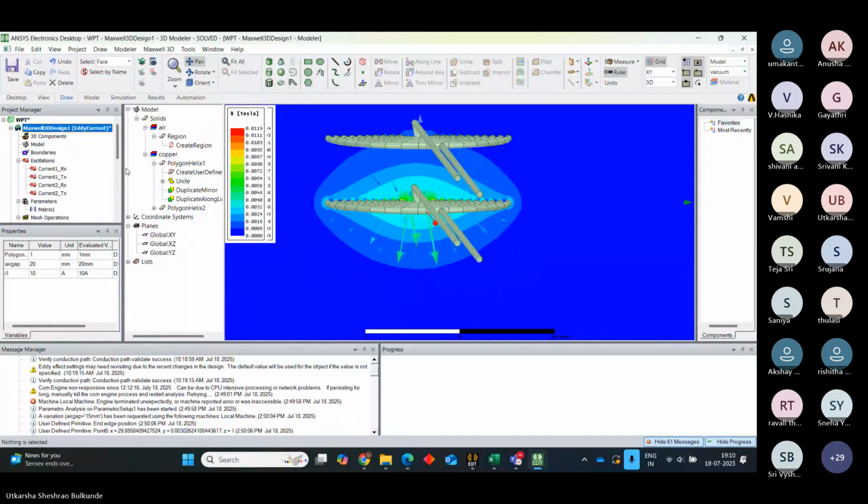So we will select a high permeability material, usually ferrite, which we place at the bottom part of your transmitter side and above your receiver coil, to direct your flux lines in the path you desire, in this case the upward direction.